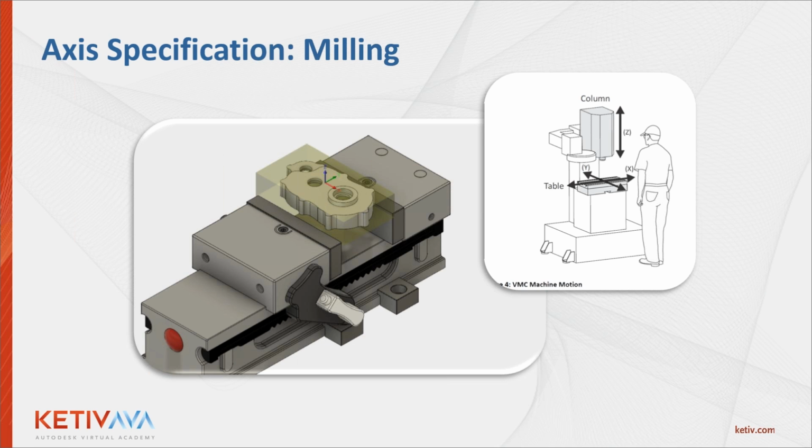All right, so another key difference between milling and turning is the axis specifications. As we see here, we have a part inside of a vise, and this part has a Z going straight up and down. You see the guy standing over there on the top right. The Z essentially goes across the height of your body, the X-axis goes horizontal, left to right, and the Y-axis goes in and away from you. So that's, again, the basics on a vertical milling machine.